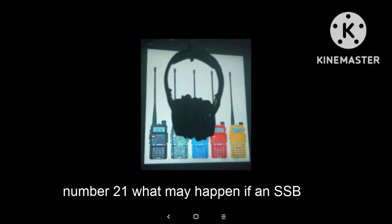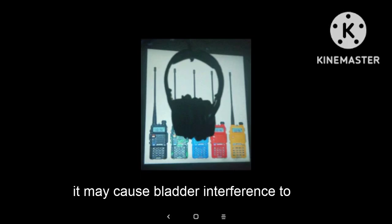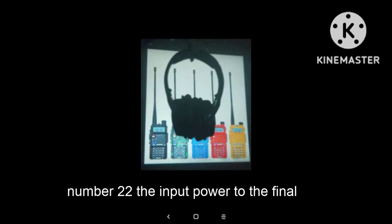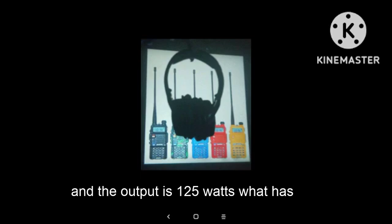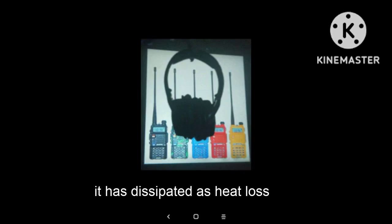Number 21. What may happen if an SSB transmitter is operated with the microphone gain set too high? It may cause splatter interference to other stations operating near its frequency. Number 22. The input power to the final stage of your transmitter is 200 watts, and the output is 125 watts. What has happened to the remaining power? It has dissipated as heat loss.